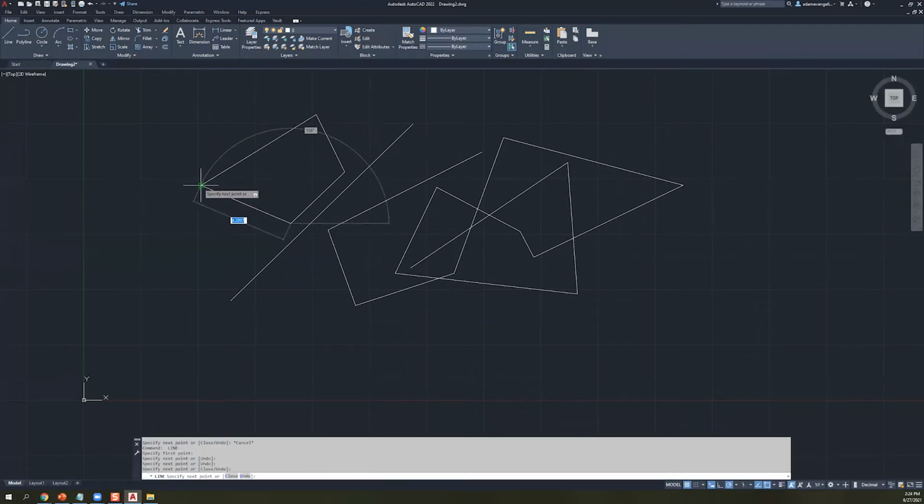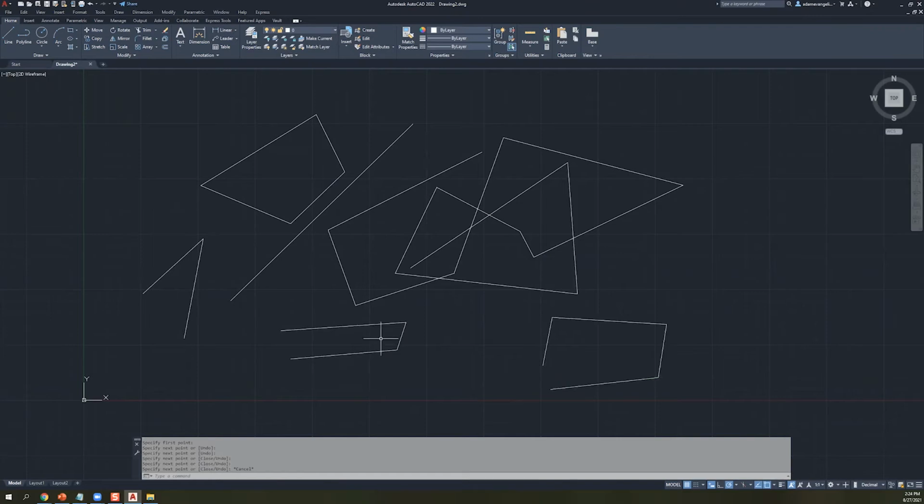So when I do certain drawings, I know people always ask, how'd you start the line command so fast like that? And I literally have one hand on escape and one finger on the space bar, and my other hand is on the mouse. I'll start clicking, right? Bop, bop, bop, escape, space, bop, bop, bop, escape, space, bop, bop, bop, bop, bop. And then you're just flying at that point, right? So that's a really common workflow as well if you need to place down multiple lines and do stuff like that, okay?